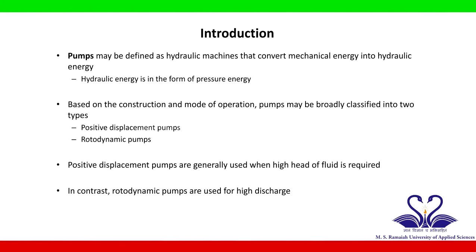Based on the construction and mode of operation, pumps may be broadly classified into two types: positive displacement pumps and rotodynamic pumps. Positive displacement pumps are generally used when high head of fluid is required. In contrast, rotodynamic pumps are used for high discharge.